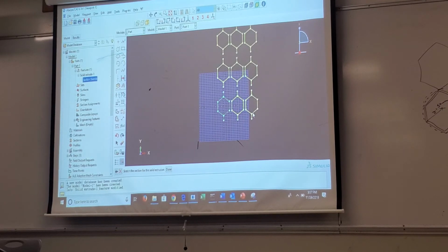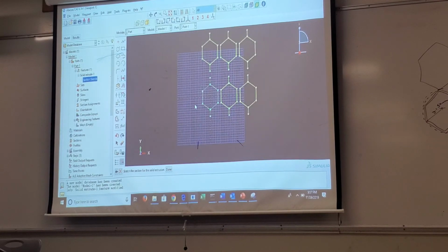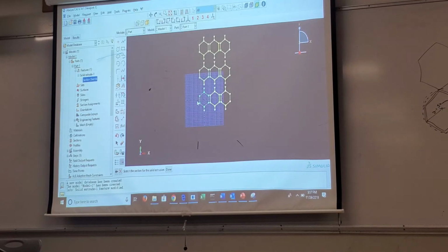So you see now there is a pattern of hexagons and they are not overlapping with each other, right? So what I did, I just created one hexagon and then created a pattern, a 3x3 structure. And the spacings I have designed arbitrarily using trial and error, such that the hexagons do not overlap, neither in this direction, neither in this direction. So once it is done, now my job is to connect them together, because eventually they are not separated, but the cells are connected to each other.